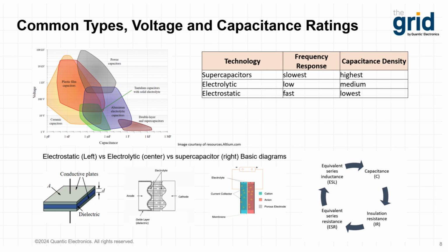Due to the unique properties of capacitor types, the use of the primary classes of capacitors in the circuit remain largely separated, while amongst the subcategories, such as aluminum and tantalum or ceramic and film, there's a lot of overlap. For example, we can see that supercapacitors are restricted in voltage, but handle some of the largest bulk capacitance needs.